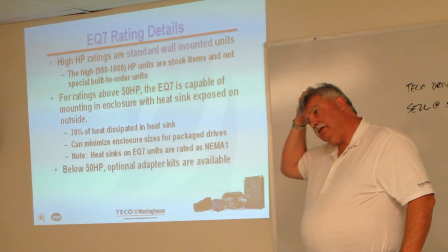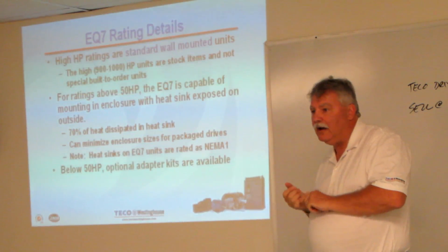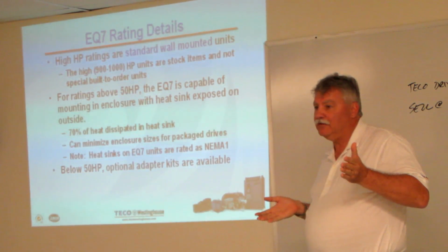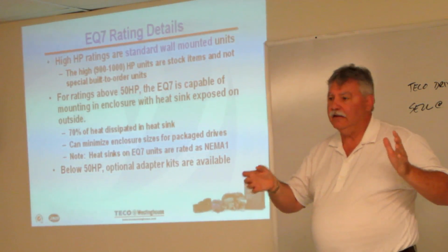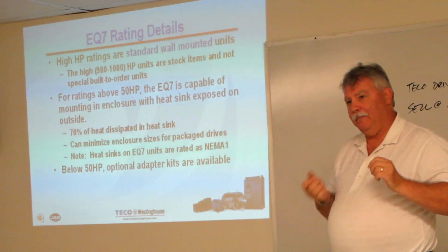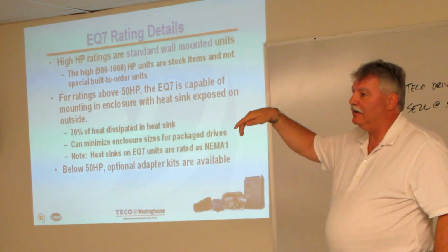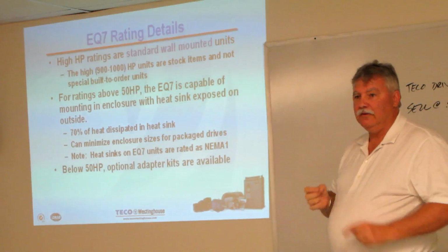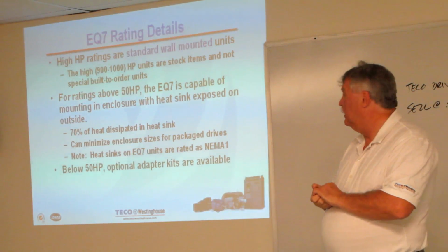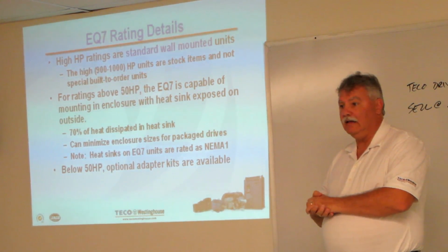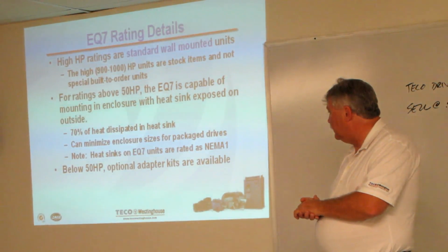If you have an application where you need to put the drive behind some sort of a protected enclosure, it's a NEMA 12 or a little more severe duty, a NEMA 3 outdoors, or even a NEMA 4 application. This is designed so that the heat sink can be mounted out the back of that cabinet. The important thing there is drives give off a lot of heat. The heat sink's going to take 70% of that and have that outside the unit. So this may save you having to put an air conditioner inside the cabinet, or if you do put one in, it'll minimize the size of it. So that could be an installation advantage and a cost advantage as well.